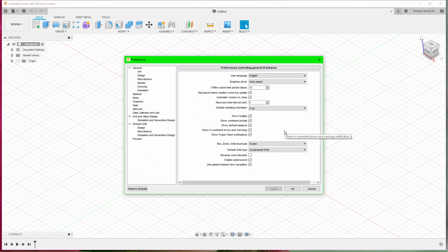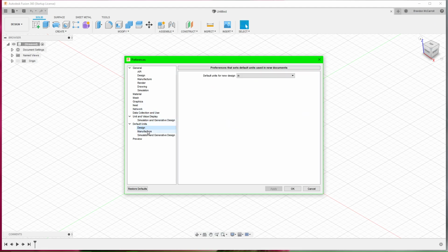Now, when we're making 3D files for 3D printers, we're going to make sure that our Z-axis is up, alright? Because on our printers, the Z-axis is up. That ensures that whenever we send it over to Cura, we don't have to do any excessive rotating or anything of the sort, okay? And then if you look right here, you can see our units. You may prefer millimeters or inches, whichever unit you prefer to use right here, okay?